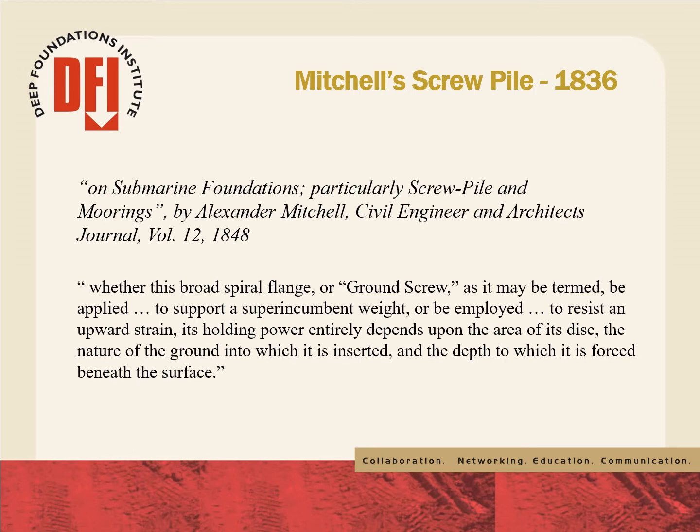Mitchell authored several technical papers. This slide shows an excerpt from one of his papers published in 1848. Mitchell cites the three basic design parameters required for helical piles: minimum depth, soil strength, and bearing area of the helix.